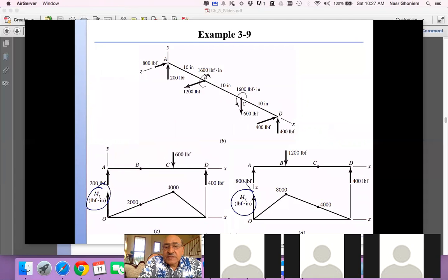We discussed last time that maximization of the moment can occur at different points. So we choose critical points B and C. We have the choice here, and we look for the 4 different values of the moments, and then we find the axial stress as a result of the combined moment with the formula that we discussed before. So this is one type of loading.